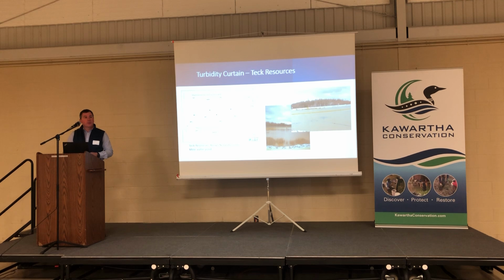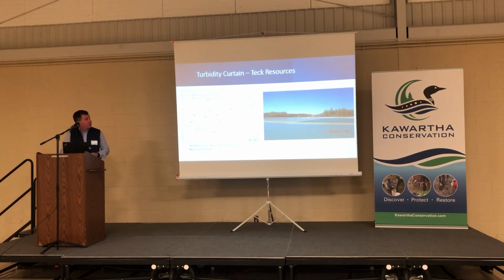This one here, up in Rouyn-Noranda, Tech Resources, the particular owner had this type of issue where their water pond was full of turbid water. So we worked with the design engineer to create a series of curtains that divided that pond into 3 different zones. And the end result is a series of zones that allow the sediment to settle out so they can easily draw from cleaner water and use it within the operation.